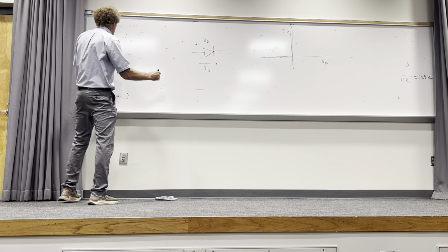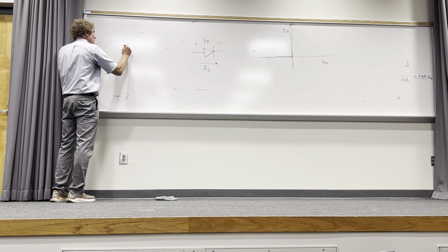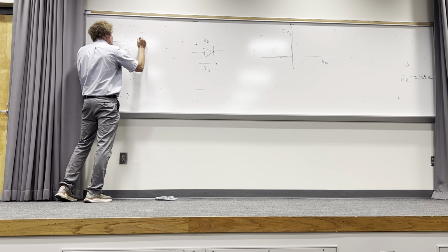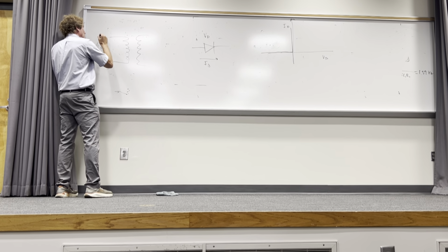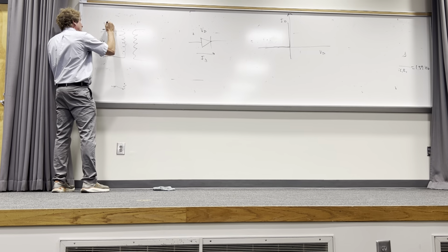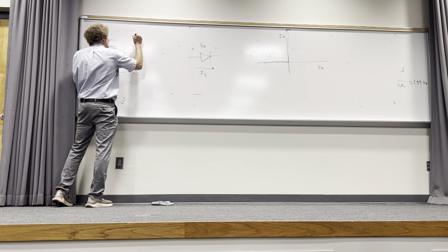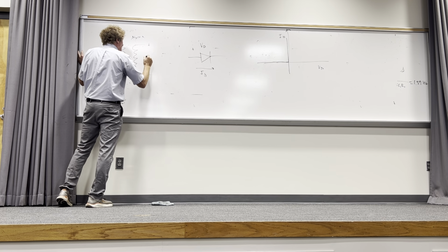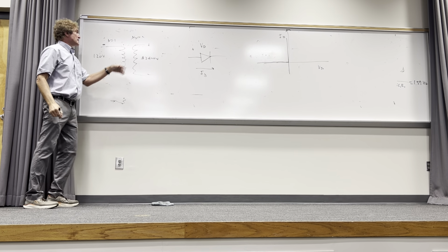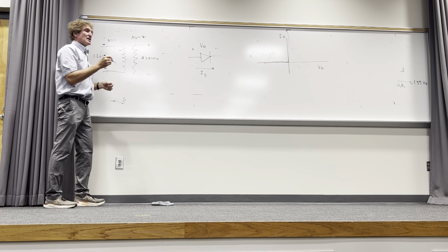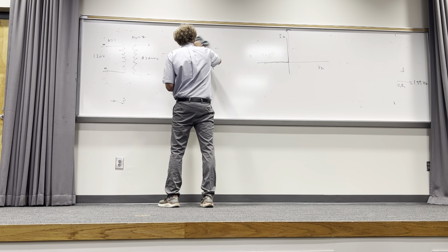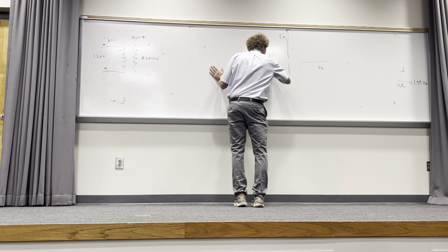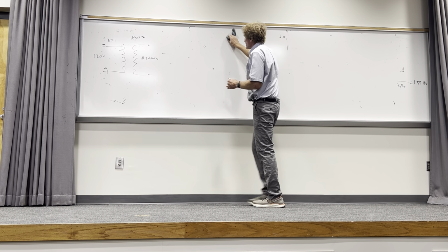So what do you do? This is my last point. It's the simplest possible thing. They will have a transformer, and I'm going to say this one is 120 volts, and put the dot here, make N1 equal 1, and N2 equal 2. So then you would get basically 240 volts here. Y'all follow me? Let me just finish this thought and you'll get it. This is the only thing I absolutely want to get to today.